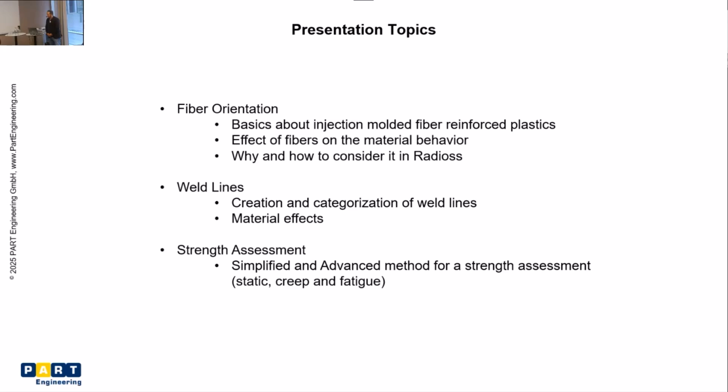Maybe not the first thing that comes to your mind, but also very important, and everyone who works with injection molded plastics knows them, are weld lines. These are the spots where 2 melt fronts meet again, and they can be very crucial to your mechanical performance. And in the end, I will also show you how to consider this for a strength assessment of such parts.